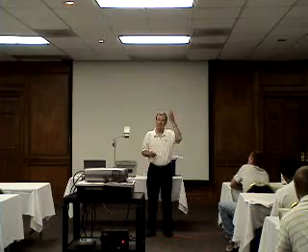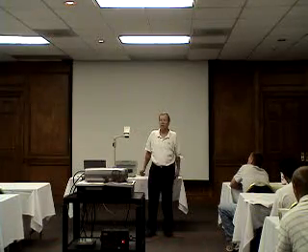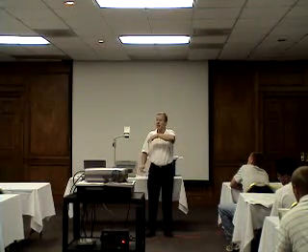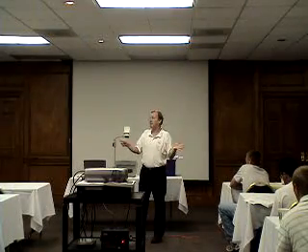I mean, it's nothing unusual to have been running a mix for a while and everything been going smooth, and all of a sudden, you don't know it, they change the screen at the quarry on you or something and send you a little bit different graded material, and it screws your test up, you know. It gives you different results, and you have to make adjustments. Well, those things are going to happen.